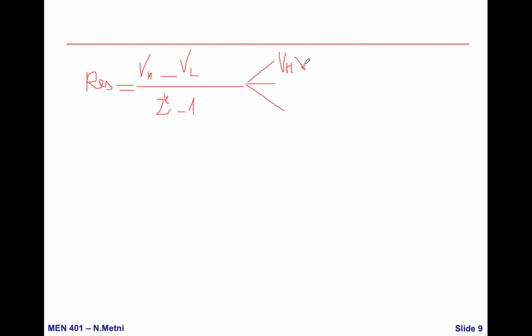This can be applied if I know that, for example, my sensor voltage goes from 0 volt to 3.1 volt only. Why should I put V high equal to 5 volt and lose everything between 3.1 and 5 volt? I will be losing all of this range.